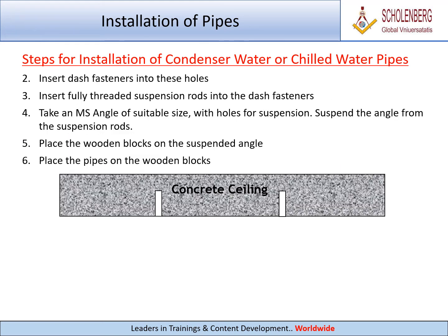2. Insert dash fasteners into these holes. 3. Insert fully threaded suspension rods into the dash fasteners. 4. Take an MS angle of suitable size, with holes for suspension. Suspend the angle from the suspension rods.